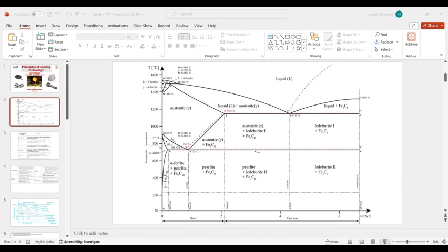But when we talk about stainless steel or mild steel, we talk about toughness, because these alloys have optimized hardness and ductility values. You can go with applications which need a little bit of brittleness, and also applications of deformation. So toughness is basically a mixture of hardness and ductility at an optimum level.